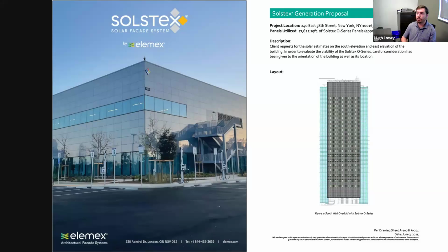Yeah, 100%. So we haven't done the 2x4 large missile impact for this product yet. It has been through significant hail testing, but we haven't had impact testing yet. We have been through wind load testing with this in regards to Miami-Dade, and we're in the process of completing that approval. We just didn't know how it was going to stand up to the impact testing itself. So we would recommend putting an impact resistant barrier behind it, but it can stand up to the high wind loads.